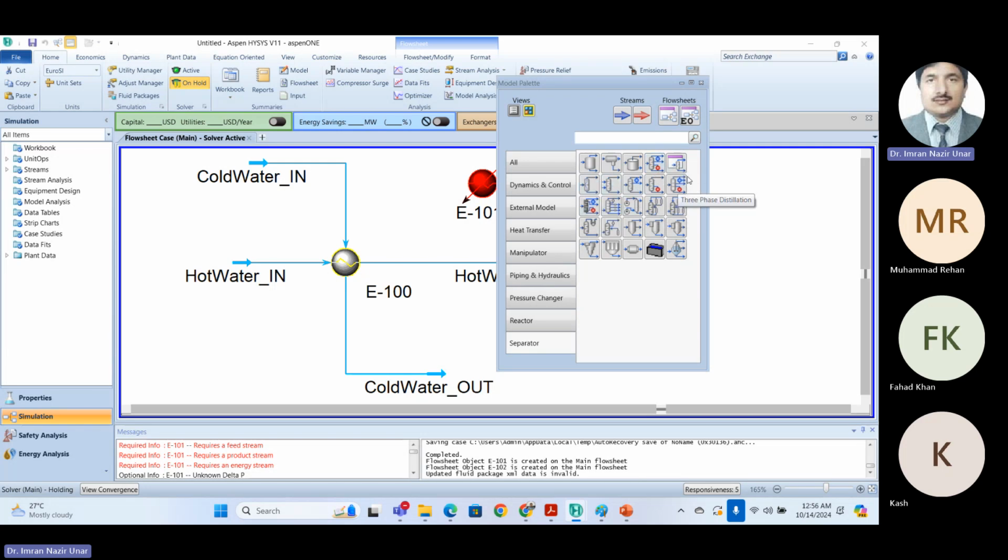Similarly, absorption and liquid extraction have their own meaning, but these first three are the very simple ones. ठीक है ना, ये आपके बिल्कुल सिंपल हैं, but the rest of the separators have some specialties. When we start the separator section, there will be a first lecture on the reasons for the operations after the flash separator, and when each is used. The question is, for example, when you have to use distillation. A rough rule is that if we have a high relative volatility, for example more than 2, then we can use distillation in a good way.